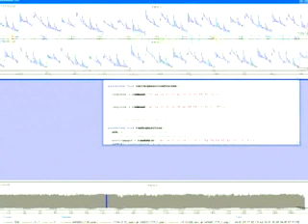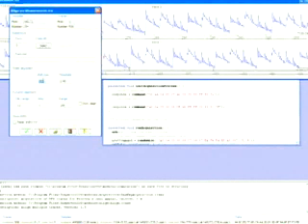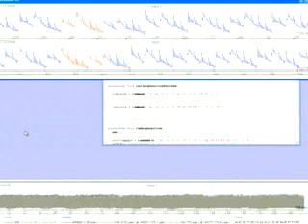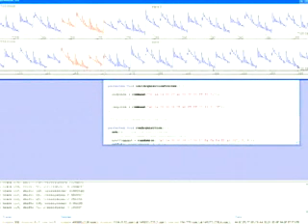So I'm just going to select one clock cycle and perform a pattern match with all the other traces. That's too much. Yeah, too much. What should I take? It's 105. Okay. And this match will just align all the traces. So this is just a pattern match. It's just searching around in every trace for something that looks a bit similar with a limit shift to the left and the right so that it doesn't go over the whole trace. And then at the bottom, well, it's just finding all those shifts. So this takes a little while.